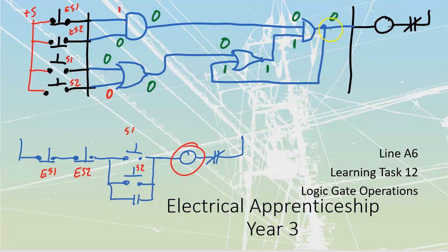Shuts off this output. That 0 feeds back up and into here. 0, which means that this OR gate, it's got 2 zeros off of it, is also going to be 0, which means that we're back to 0 inside of here. So now we get this self-feeding, this memory state that's going to go and happen. I've switched that thing off.